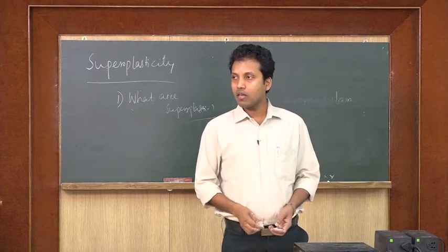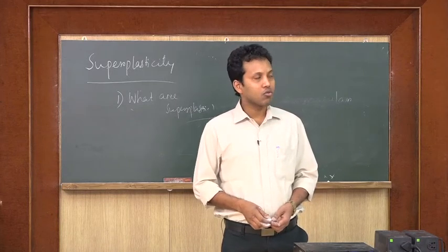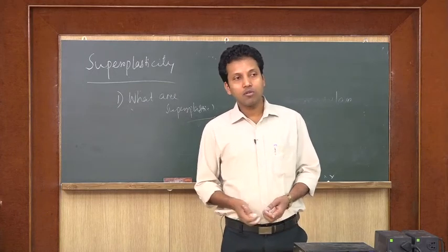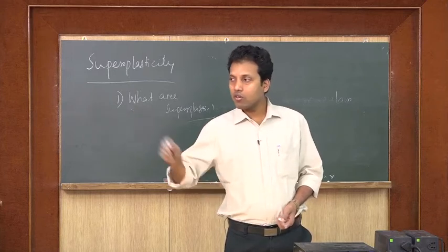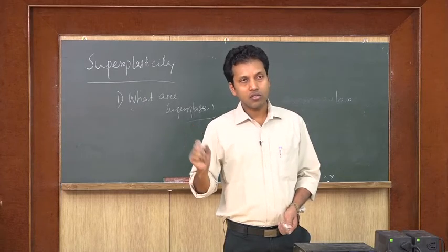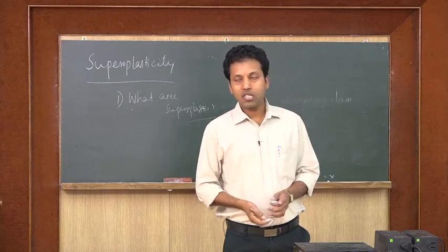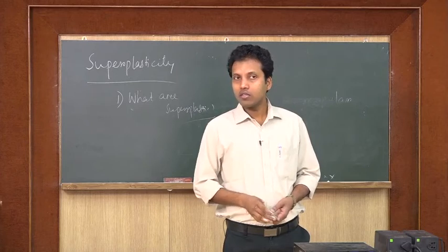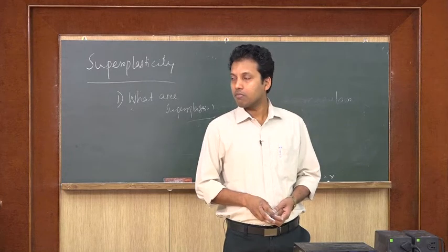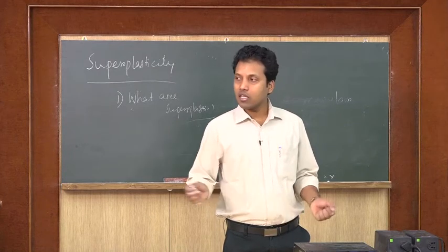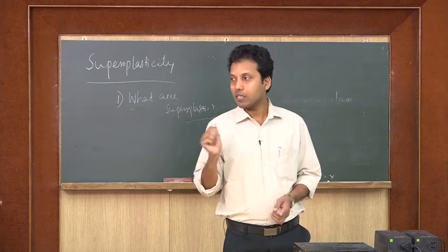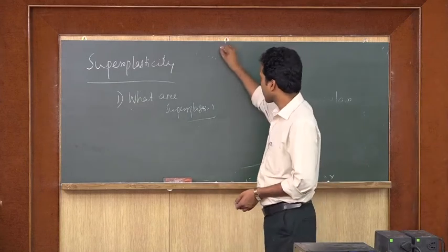There are many mathematical relationships for superplastic materials. The only thing quite known to us earlier is the point of instability. In the tensile chapter we have seen where dP equals 0. So, dP not equal to 0, or we have dσ/dε equal to σ. So, dσ/dε greater than σ, those things we can write mathematically for the superplastic behavior of a material, that you can check.